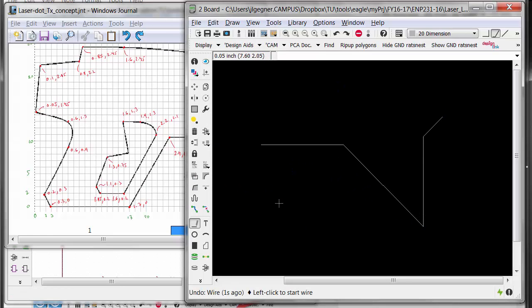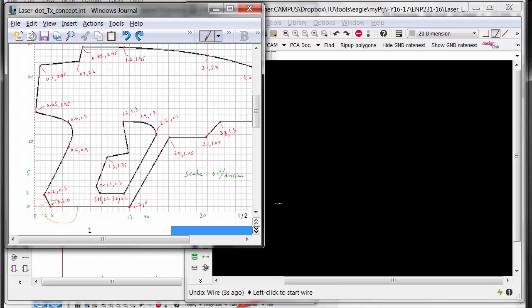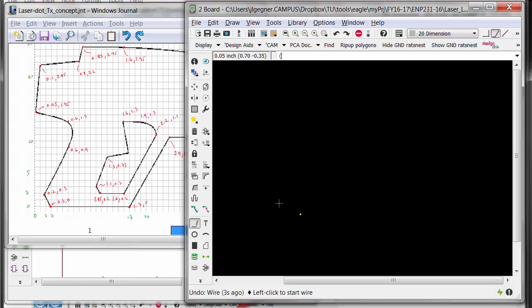I can enter coordinates, but instead of clicking, I'm going to type coordinates in. It's much faster. So you have to have clicked wire, or you have to have typed wire. And then up in the edit box here, I'm going to start entering coordinates. I'm going to begin in this bottom left corner here, and I'm going to work my way clockwise. I won't do all of these, I'll just get started. Okay, so you do open parenthesis 0.3, space 0. Then 0.2 space 0.3. Zoom in here.